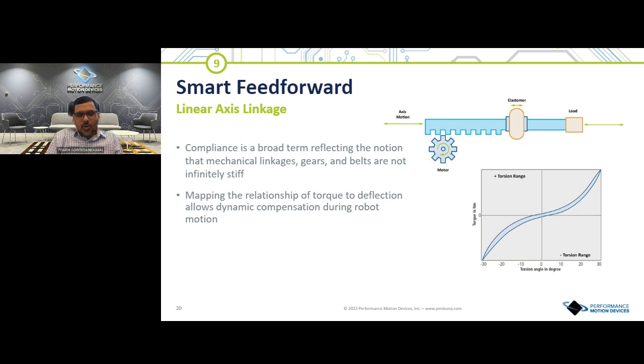We've also seen this used for other use cases where they have an older encoder that's not as accurate, and they can't afford to use a higher cost absolute encoder. So they use this feed forward so they can calibrate it in the lab and compensate the position feedback. They add a feed forward table, so the position feedback that comes back gets compensated to be much more accurate, as if it were an absolute encoder, and then it's used in your position loop. So there's techniques to get a lower cost hardware implementation to perform like a higher cost absolute encoder with feed forward tables. We can work with you as a partner: once you pick these components, we can help you cost optimize them and provide you motion techniques to make them work better.